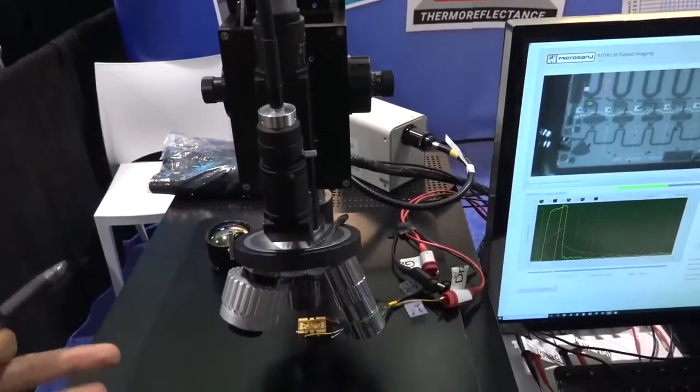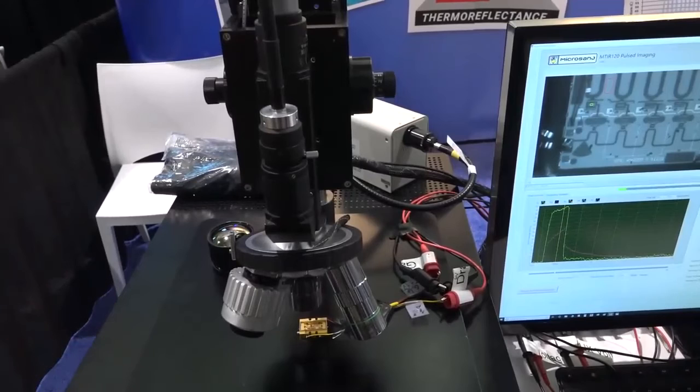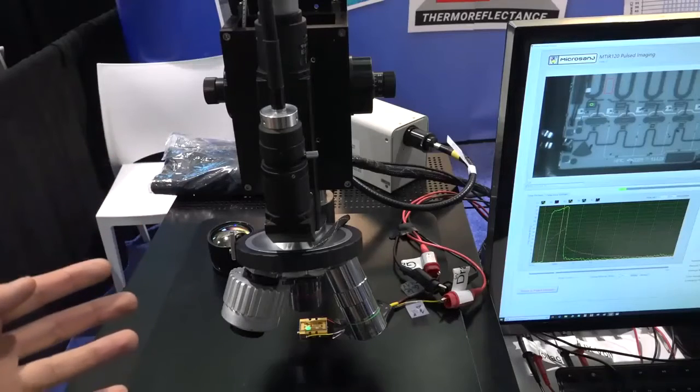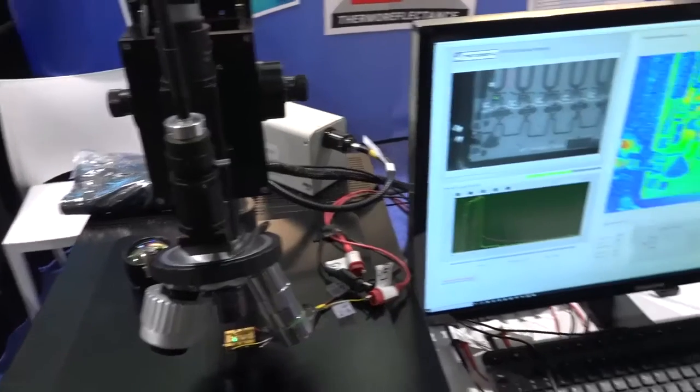And this allows you to be able to do frames as small as a nanosecond. So you can capture rates so high that you can see the flow of heat due to the flow of electrons in a MMIC with the resolution you would expect to see from an optical instrument, which is absolutely crazy. So here's an example of that.